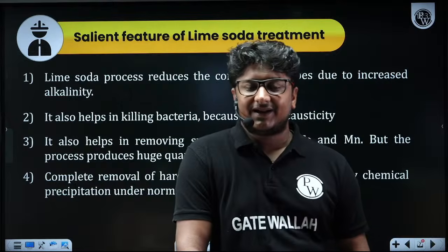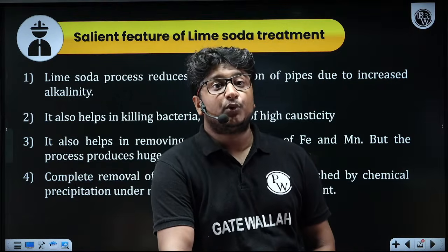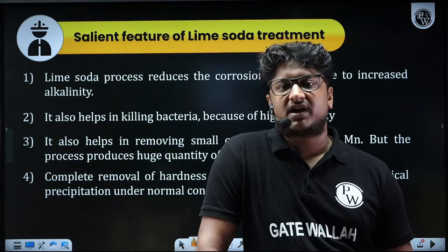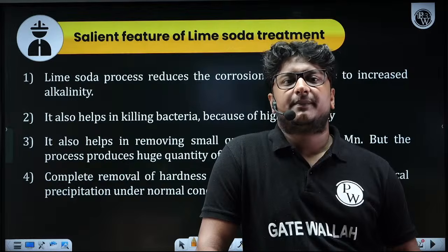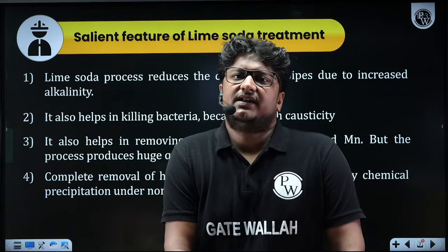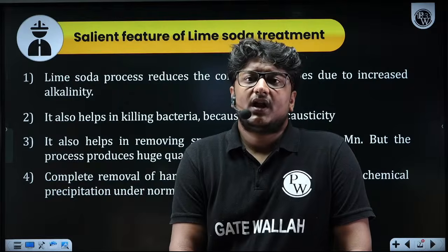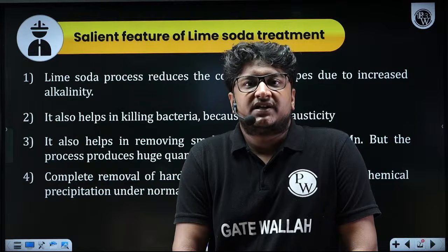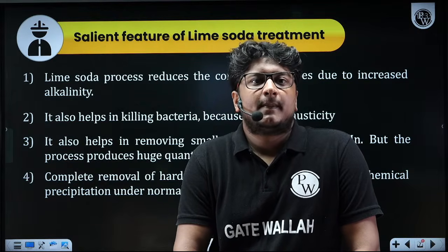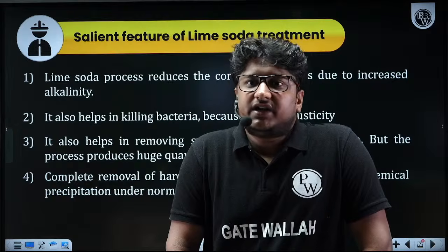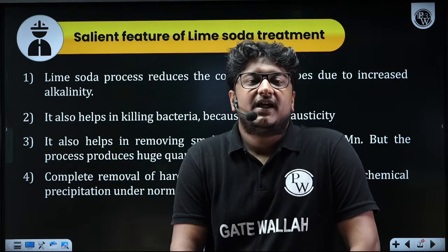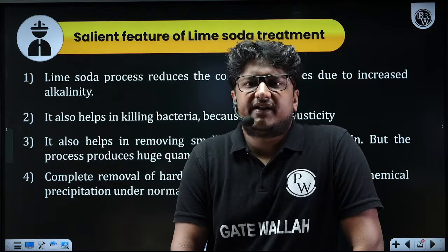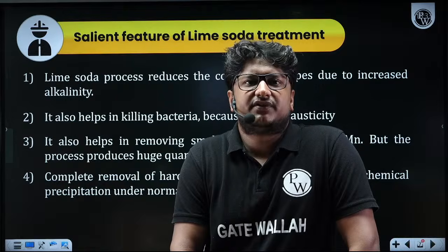Now hardness in a dissolved format is allowed up to a limit. You know the drinking water standard for hardness is 200 milligram per liter as the acceptable limit, and the rejection limit is 600 milligram per liter. So up to 200 milligram per liter it is allowed in drinking water, but in a dissolved format, not in a non-dissolved format, because non-dissolved hardness will be easily seen by the person. Nobody will drink that water.